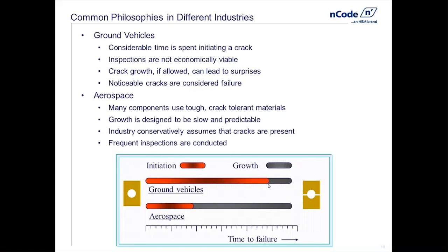So if we assume that there's a crack because of some manufacturing flaw or because of some environmental consideration, a bird strike or something, or a mechanic drops a tool and dents a structural member, let's assume that's a little crack, and let's design that member so that it won't grow so fast as to cause immediate failure, but it will grow over the next year, for example. And when it does fail, it'll give some kind of warning, some kind of visual warning, or some kind of inspection technique will allow us to find it.